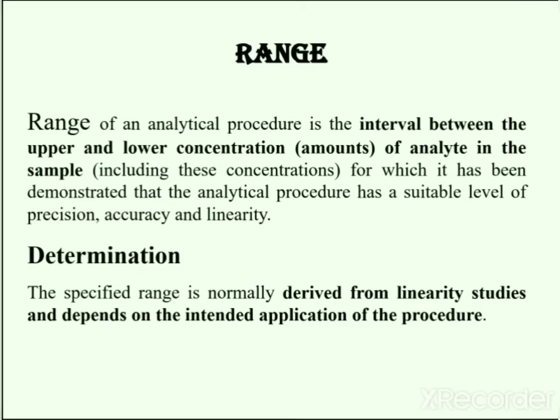Next performance characteristic is range. The range of an analytical method is the interval between the upper and lower limits that have been demonstrated to be determined with accuracy, precision, and linearity. For example, upper and lower concentrations of analyte in the sample. This range will be the concentration range in which the linearity test is done. In the analytical method validation, a specified range is generally derived from linearity studies, and it depends on the intended application of the procedure.